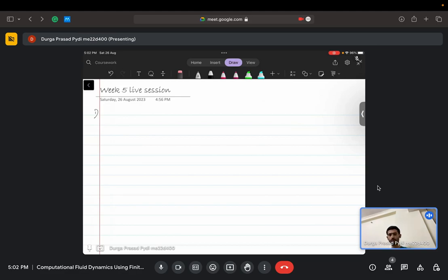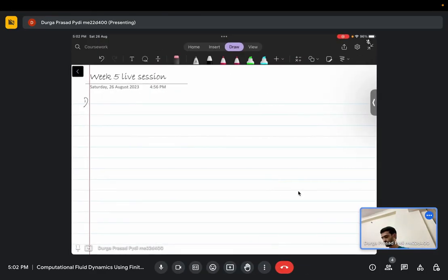So what we are trying to do: we have a source term given by the form S equal to a minus b phi mod phi. When we take the normal 1D heat equation or some diffusion equation, this can be reduced to linear form only when we have S expressed as SC plus SP times phi.